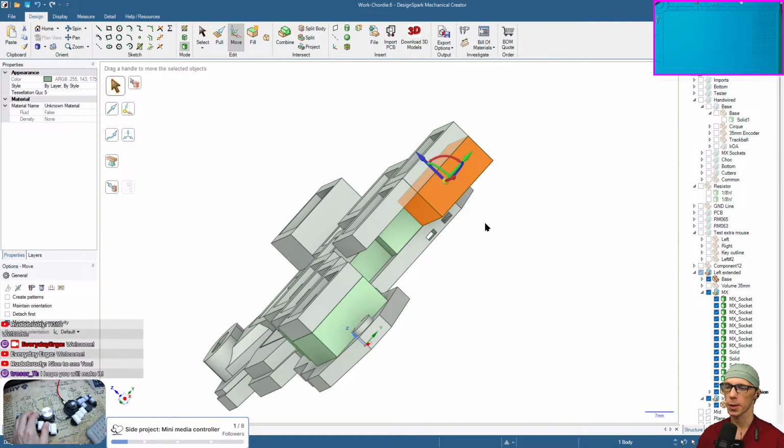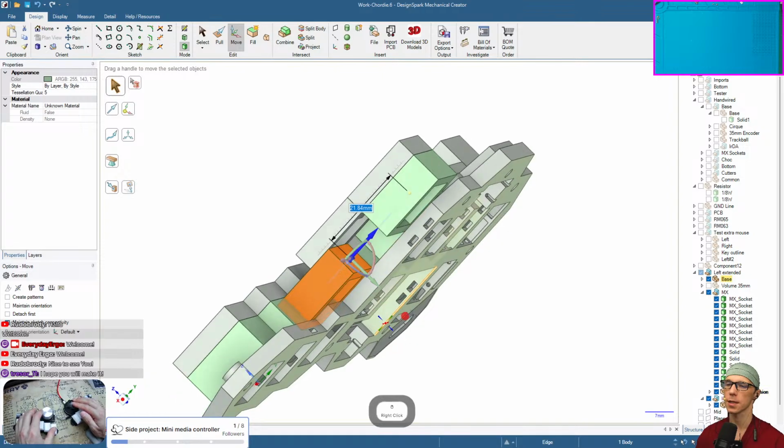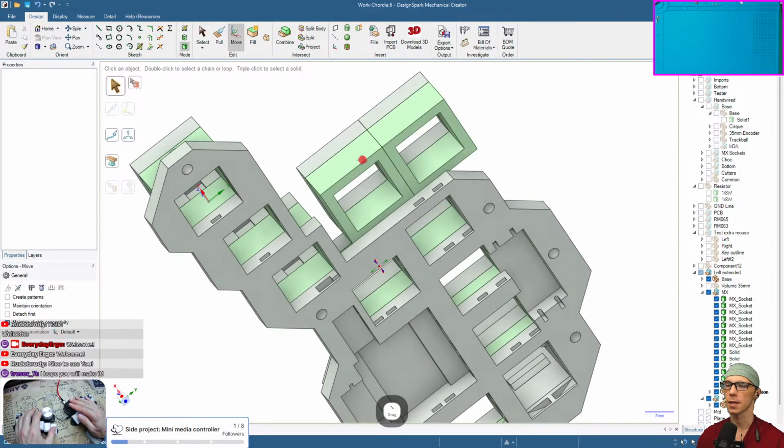So I just copy and paste another column. So I can move it, for example, all the way here. And then I can press A for anchor. I can select this wall. I can select this direction because I want to move it in this direction. I can press U, which means up to. I think I also set up this as a shortcut, or maybe it's by default. And then I can show where I want to move it. So up to this wall, and it's done.